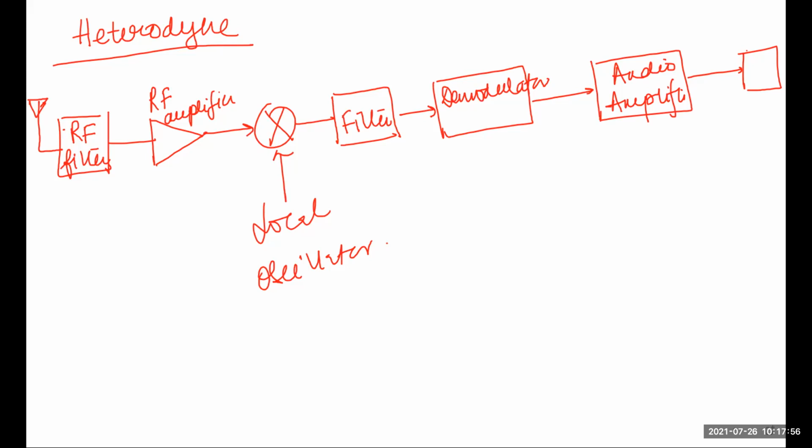See, we always know homogeneous means the same frequency or the same parameter. What does heterogeneous mean? This word heterodyne has come from heterogeneous. Heterogeneous means different, 2 other, 2 different frequencies or 2 different parameters. So from there heterodyne has come. Heterodyne means 2 different frequencies. So for the combination and mixing of 2 different frequencies, this heterodyne device is required.